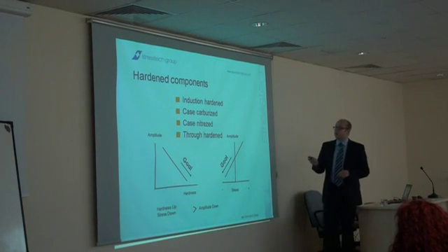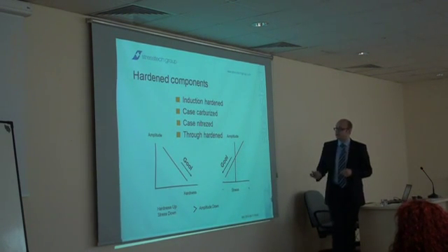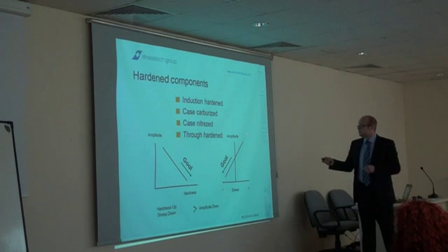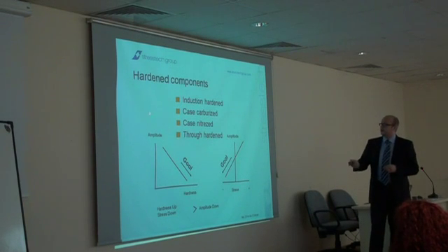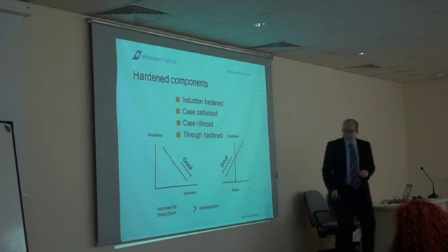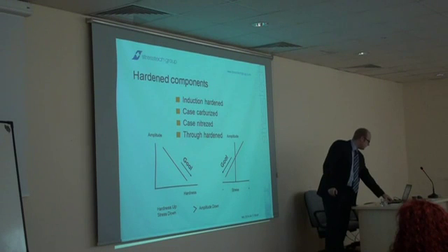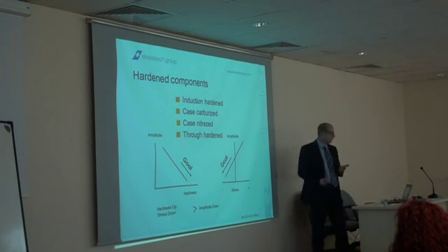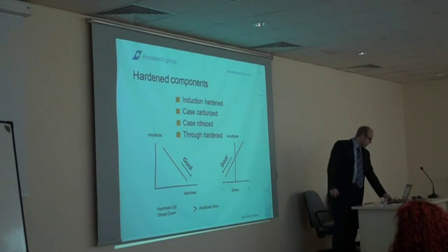And for example, hardened components: our goal is that we get the hard material, of course, and we get compressive stress in our sample, which means that we get a low signal from Barkhausen, because it's very sensitive both to hardness and to residual stresses.